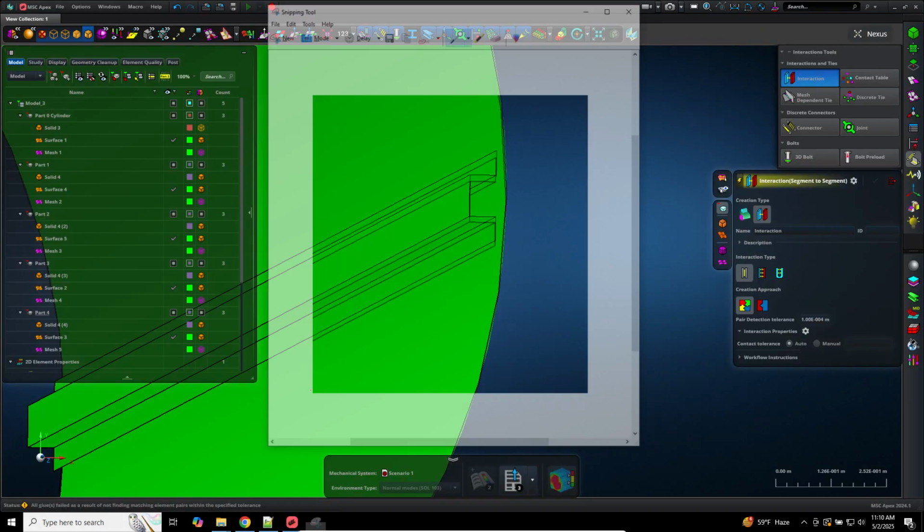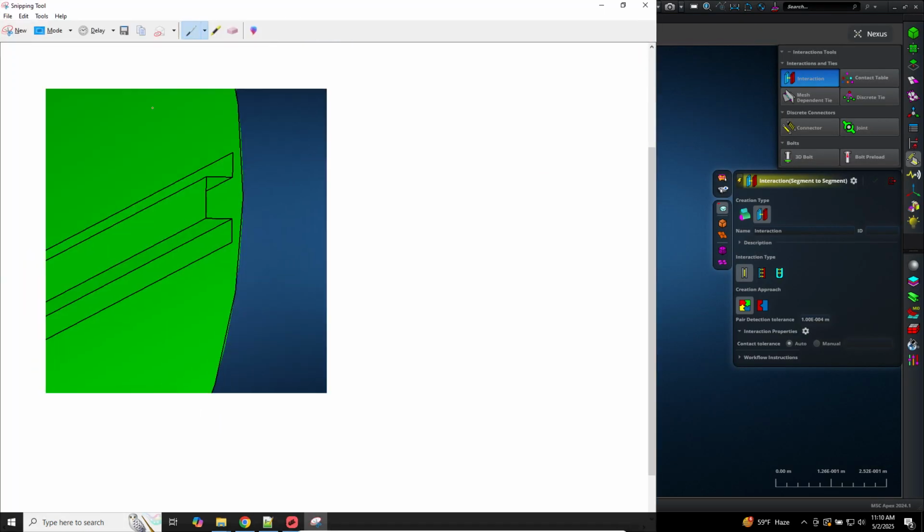So let's go ahead and select this. And let's draw a small sphere, if you will. We're going to say that this sphere is, what did we say it was? 1e negative 4. You notice that these spheres do not intersect. They don't overlap. So the algorithm is not going to detect contact.